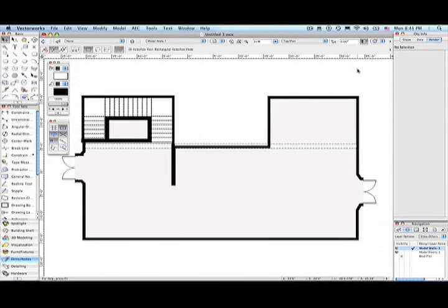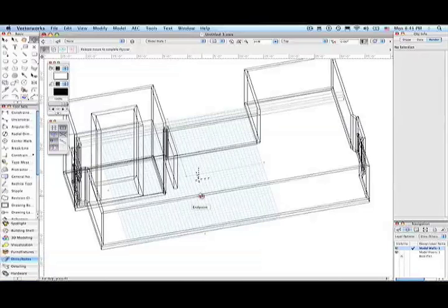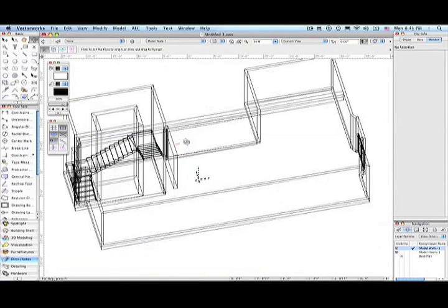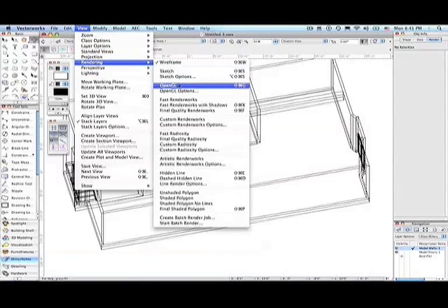So here's a network of walls. It's in top plan view. It's the studio. It's the art gallery that we looked at from the week before. I'm going to flip this up into 3D so that we can take a look. What I'm looking for is the edge of the top of the wall, and I'm going to use a tool called the extract command to do that.